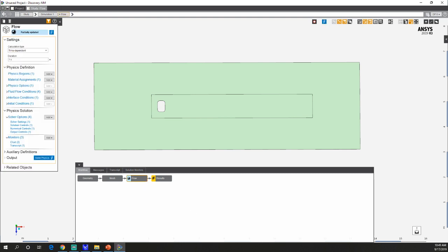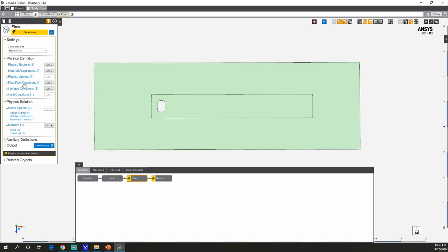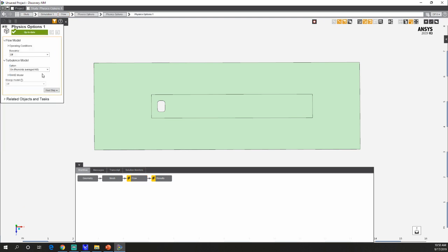So lastly, I wanted to switch this back to a steady state because I want to run one more thing and show you. AIM by default switches to some of the most advanced options available, but we have the option of picking different turbulence models. There's even the option of doing boundary layer transition, so laminar to turbulent transition, if you want really high accuracy simulations. We've done this for curvature correction for highly swirling flows, such as pipe flow or flow around a rotating disk.